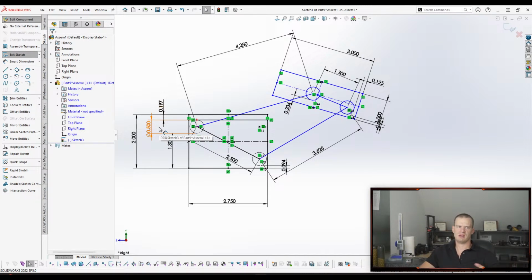So yeah, as far as how do I make things adjustable: one, top-down modeling; two, try to use dimensions as sparingly as possible, try to use relationships when you can; and three, use the patterning tools. That would probably be the core class of how to do parametric well. I hope that helps. If you got any more questions, feel free to put them in the chat.